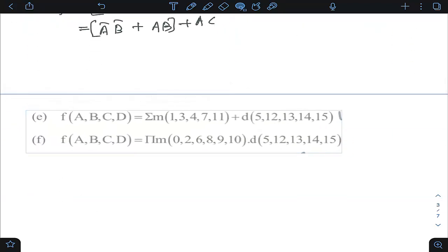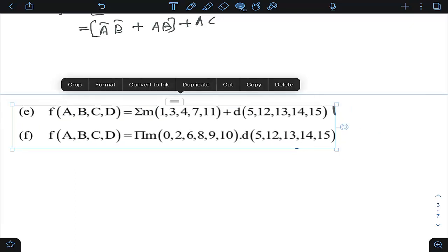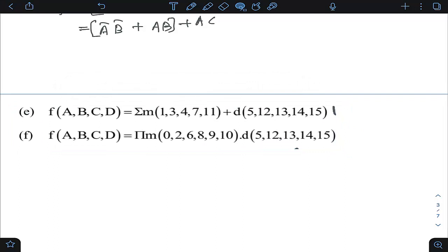A certain fact you should know, students, is that don't care combinations can be used as per our convenience. But for min term case, when we are solving, all min terms should be grouped, or all max terms should be grouped. While dealing with don't care, it is not compulsory that it has to be grouped. You may have situations where you have done the grouping and certain don't cares are left, so it's okay. But your goal is that no minterm should be left if you are getting an SOP expression, and no maxterm should be left if you are getting a POS expression. But don't care can be left.